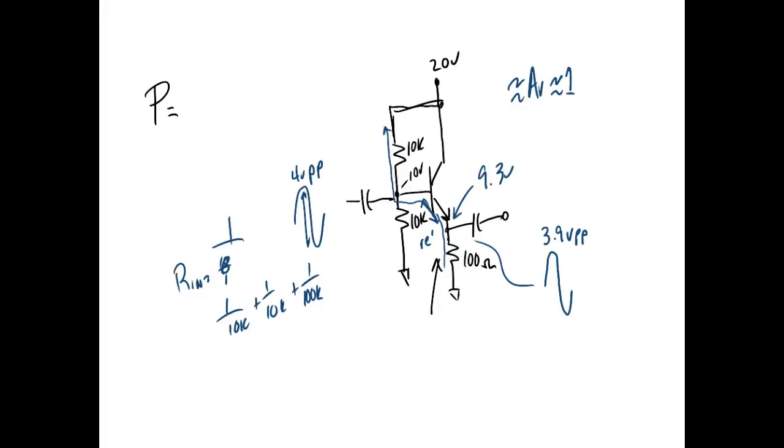But I can get my voltage gain out of common emitters, right? So I can get plenty of voltage gain with a common emitter. It's just when I need to drive those low impedance loads, those speakers or those guys that require a lot of current and a lot of power. So power means current, right? Not only does it mean voltage. So I don't get any voltage gain out of the thing. In fact, the voltage gain is going to be less than 1.